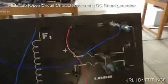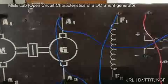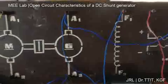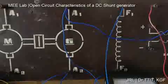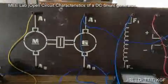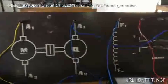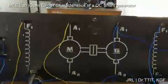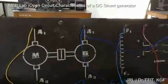We are not connecting any load across the output of the generator. Hence, this is called open circuit. So the generator is open circuited, and the characteristic that we are going to find out is called the open circuit characteristic. Ultimately, what we are going to find out is the critical resistance of the generator. We can find the critical field resistance of the generator by plotting the open circuit characteristics.